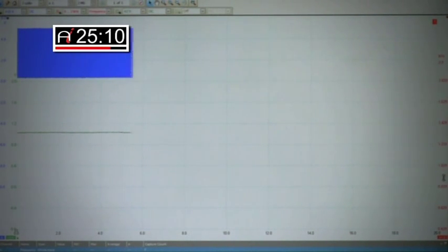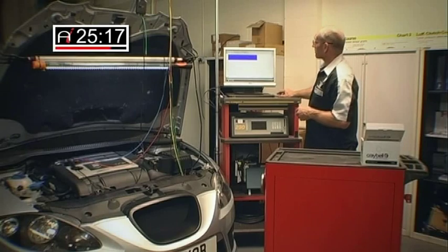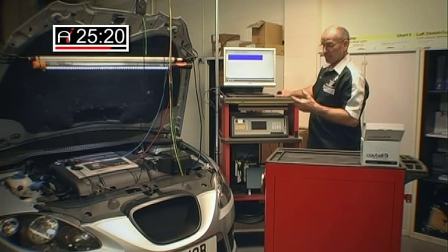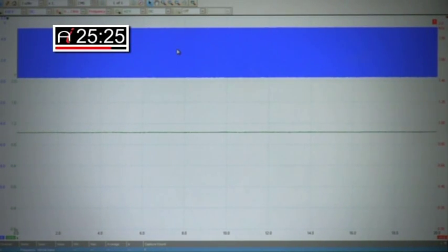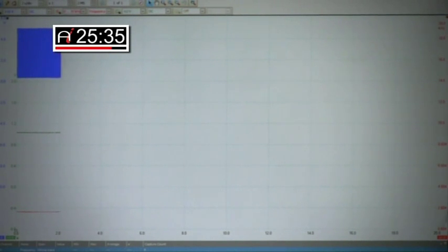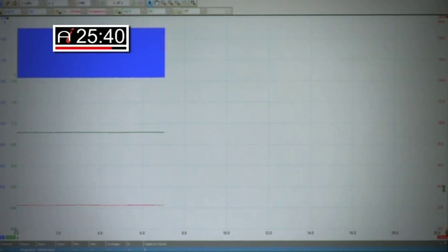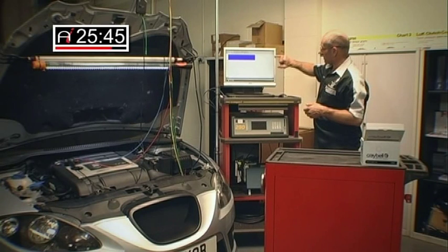I now need to look at range, because we're already at 2200. We have a 0 to 2000 range, so we're going to get no display because we're already above that reference. The next range is 0 to 20,000, that's ideal, so I'm going to select the higher range. I've shifted the baseline so that 0, this is now frequency, kilohertz, 0 to 20,000.